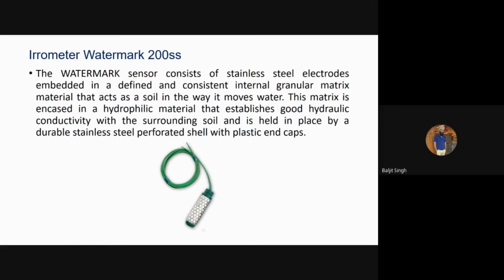This matrix is encased in a hydrophilic material that establishes good hydraulic conductivity with the surrounding soil and is held in place by a durable stainless steel perforated shell with plastic end caps. The hydrophilic material helps in attracting the water, the moisture. The outermost part is this stainless steel mesh.